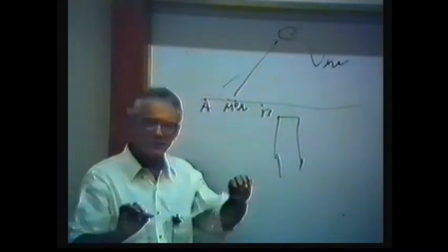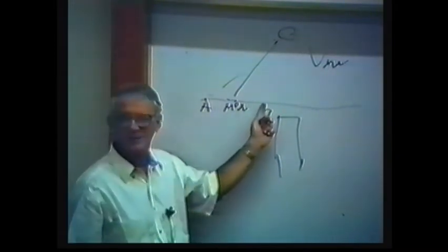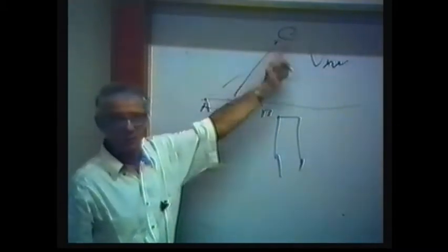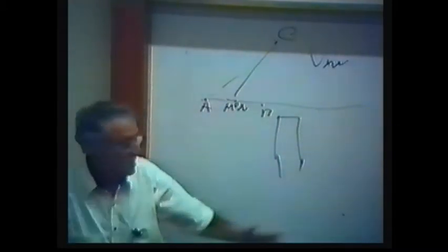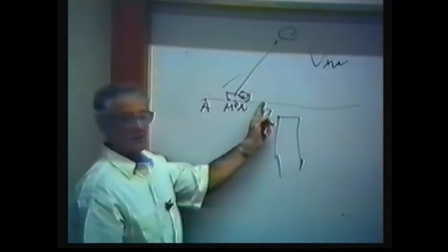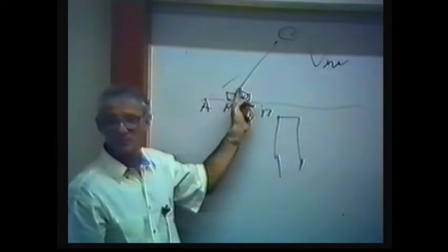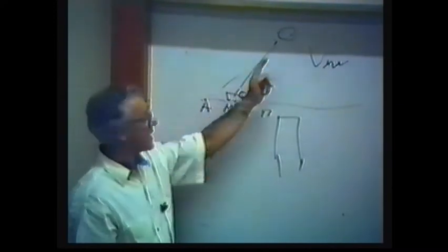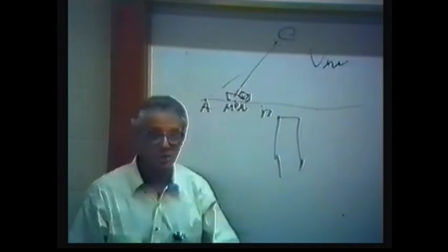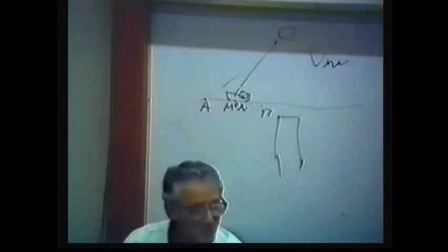Then at the same point, we change the direction of the current, so the current travels from B to C. It must be a closed circuit. So we measure voltage as before, but the battery is connected either with C and B, or with A and C. It turns out at each point we have two voltages, therefore two apparent resistivities.